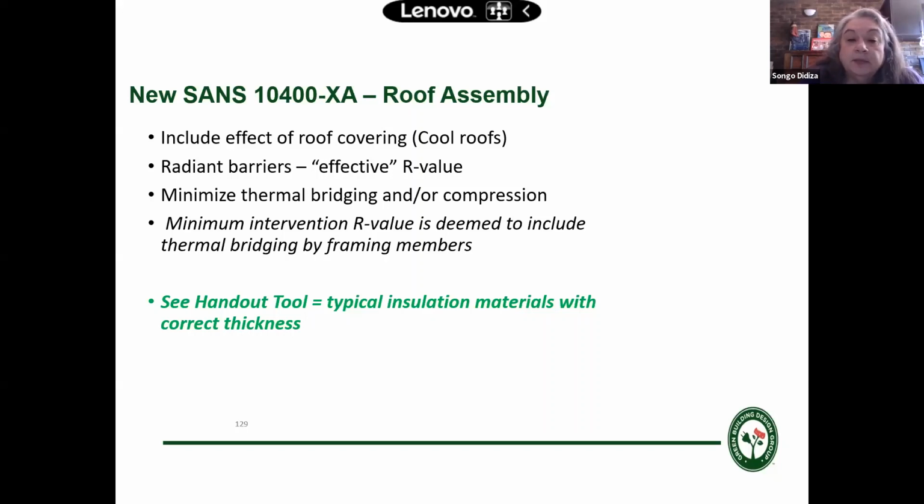And it's based on what the emissivity is. So normally I use lots of hand gestures, but as I said to you, the heat from the sun comes down, reflectance plus emittance equals 1. So the more the product reflects, the lower the emittance down into the building. So it basically just prevents that emittance going down. It doesn't work well in upward flow temperatures. So it doesn't work well for winter areas, but it does work well for hot summer areas.